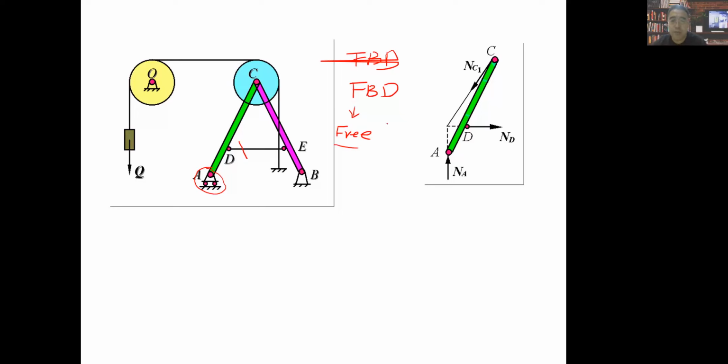But we should know in our mind that this object is always in equilibrium. So for all the constraints you removed, you must give their reaction forces accordingly. According to what? According to the type of constraint it is, right?